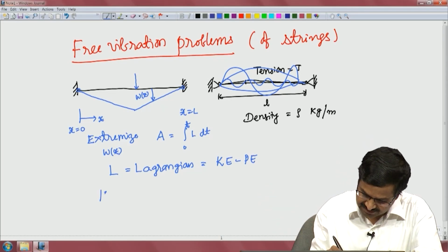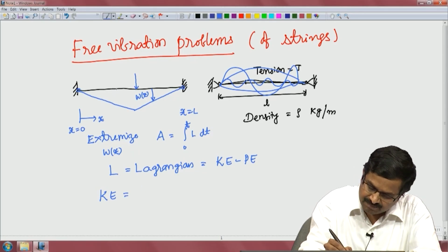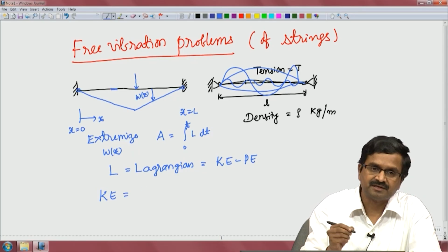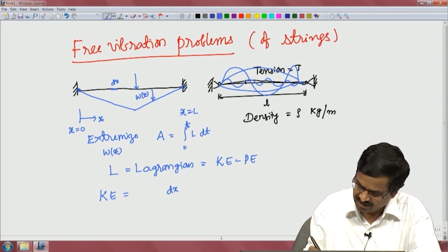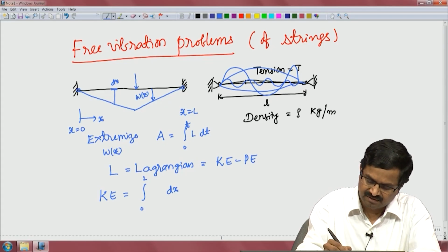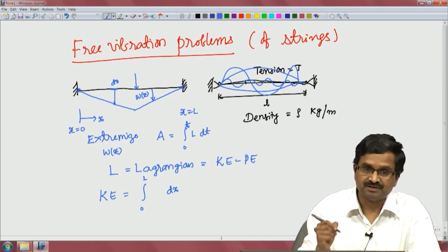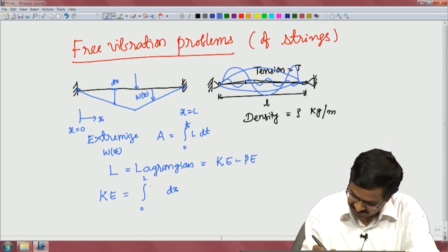What is kinetic energy for a vibrating string? So, we take a little piece wherever that is vibrating, it is a dx. Okay. Whenever there is a dx, we have to integrate from 0 to L, the kinetic energy of little thing as it vibrates by the W there. Okay. So, when we have that, then we can write it as half into mass per unit length.